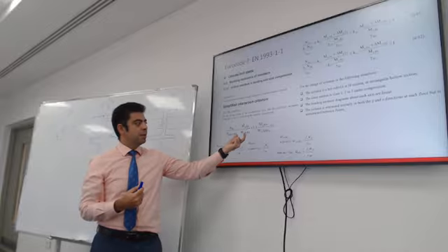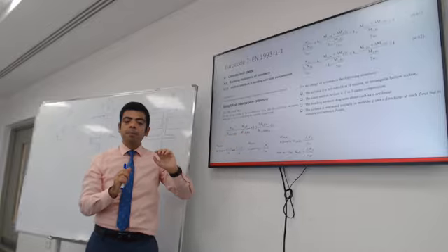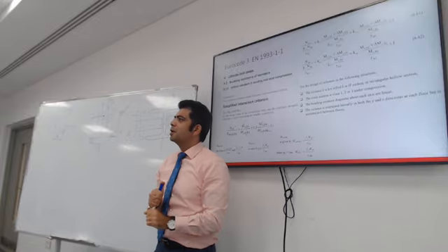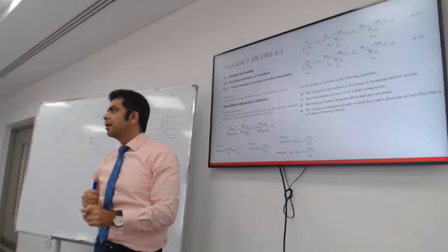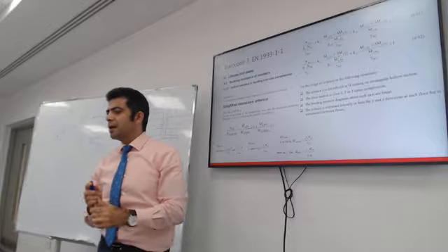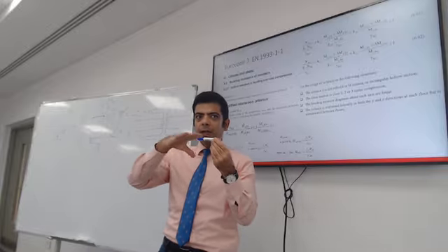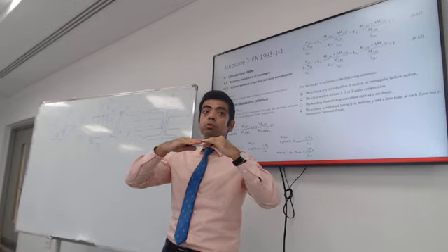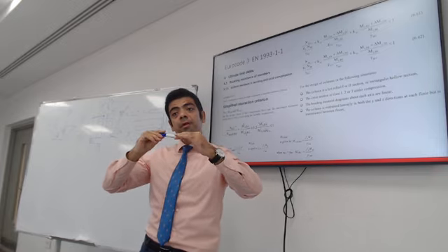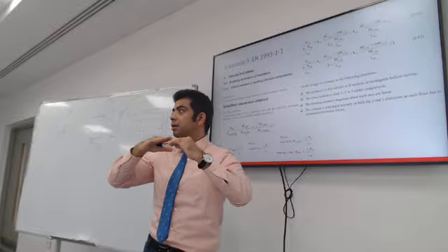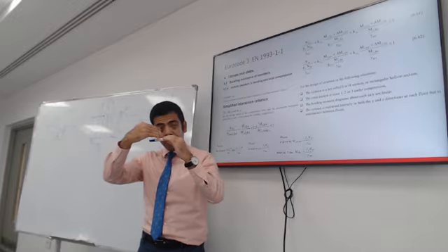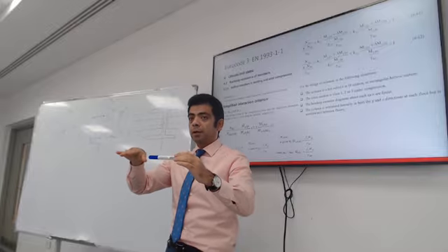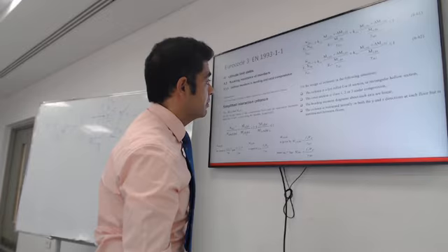The capacity for bending about y will take into account the lateral torsion buckling. Do you remember when we designed beams, we had to decide, is the beam laterally restrained or unrestrained? So what would restrain laterally a beam? If you're designing a beam and slab, if you connect the slab to the top of the beam, it's going to prevent it from lateral torsion buckling. What about a column like this?